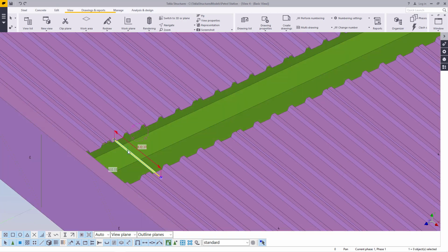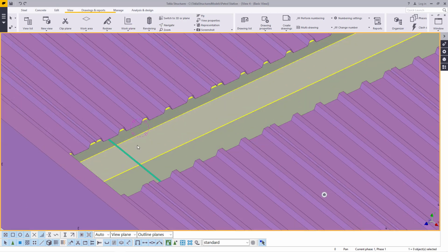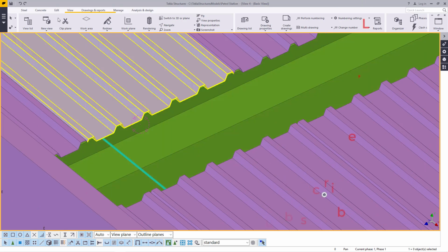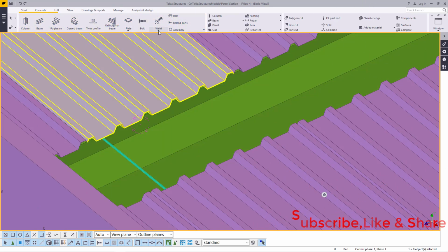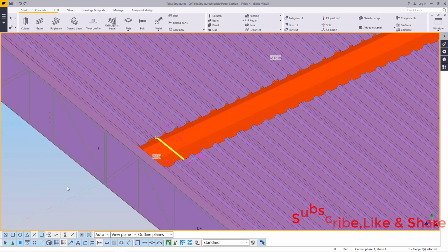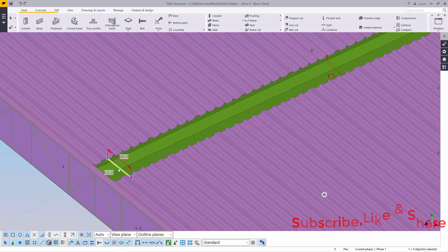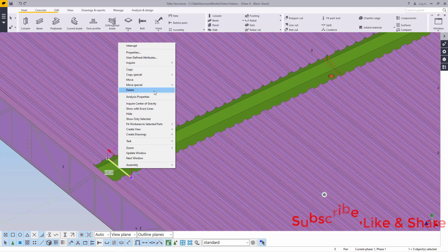So we have a rod in the center here, so I'll just select on it. We can weld it straight. Once it's there, we'll come to steel here, pick create weld, and we can weld that to that, to that. So we've created a weld, so you can see the weld. We want to populate this along this end, so I'll select on this just to stiffen our valley gutter.